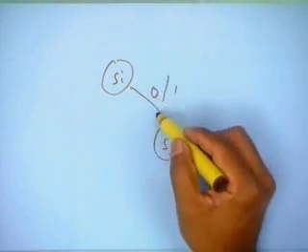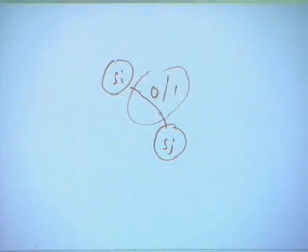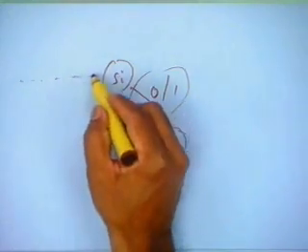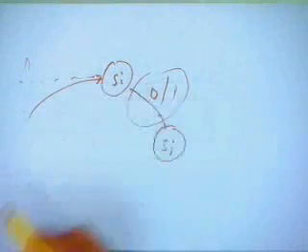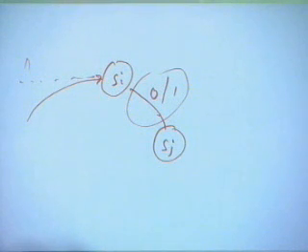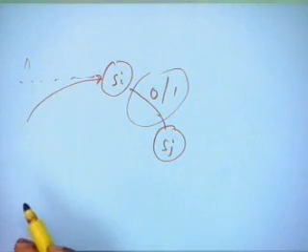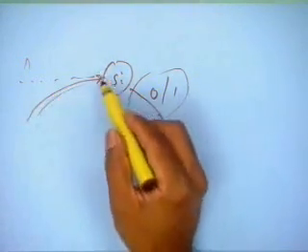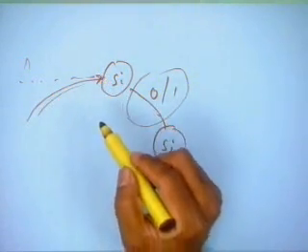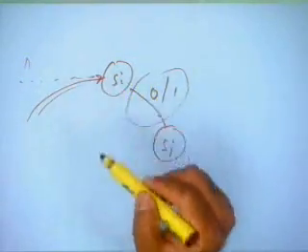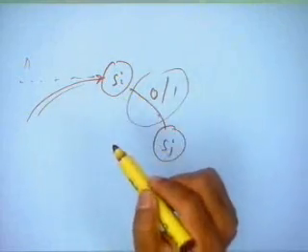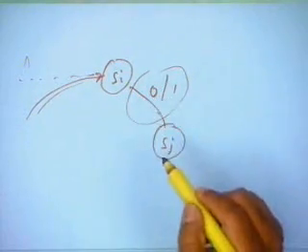If I want to verify that this particular transition occurs, what do I have to do? Wherever the machine may be, in any of the initial states, I have to take it to Si, and I have to have confidence that I have reached Si. Please remember, we are working under a condition that the machine may be faulty. So I have to take the machine to state Si, and I have to apply some input so that the machine reaches Si, and I have confidence that it has reached Si. Then I apply the input.